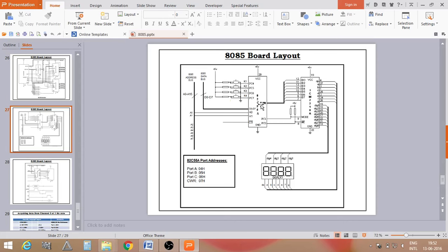So for that you have to first send the data into port B. Port B is sending data into these ID0 to ID7 pins, and PC1 and PC0 here are used to send some pulses. So this is also an output port, and port B is also an output port, since you are sending the data byte here. Alright, and port A is not used here. Okay, so let us write the control word for this.